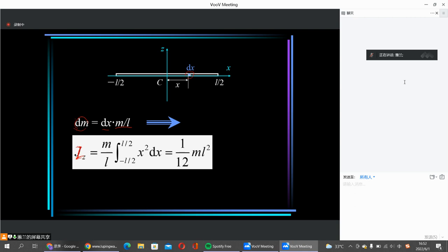So the mass moment of inertia about the z-axis, Iz, with the z subscript indicating which axis we are calculating, is the integral of x squared dm, where x is the distance from the element to the z-axis. For every element dm is m over l times dx. The density is constant, so we can take it out of the integration.